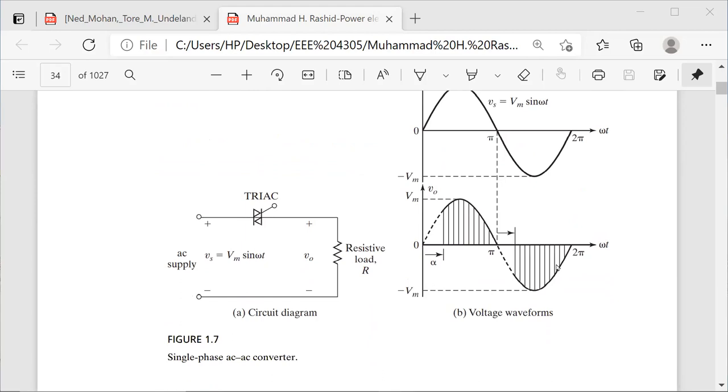So sometimes you can use the thyristor as an AC to AC converter, like the regulator switch at your home. This is the TRIAC. The characteristics of the TRIAC will be like this. It will conduct in both cycles, not like the SCR here, which only conducts in the positive cycle. But this thyristor, we look here, has back to back parallel diode symbols.